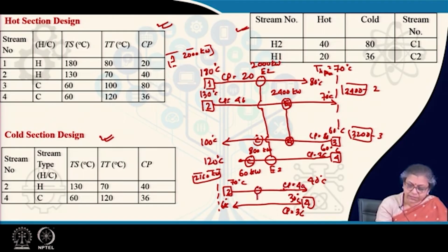So, you place a heat exchanger here. In this case, what do you find? For this the enthalpy requirement is about 1200, for this the enthalpy requirement is 1080. Quite naturally, this heat exchanger is going to be E3, and this is going to remove 1080 kilowatt of heat, so that this stream is completely satisfied. There is some excess heat which has to be removed from this stream. Since there are no other exchangers, we simply put a cooler here.